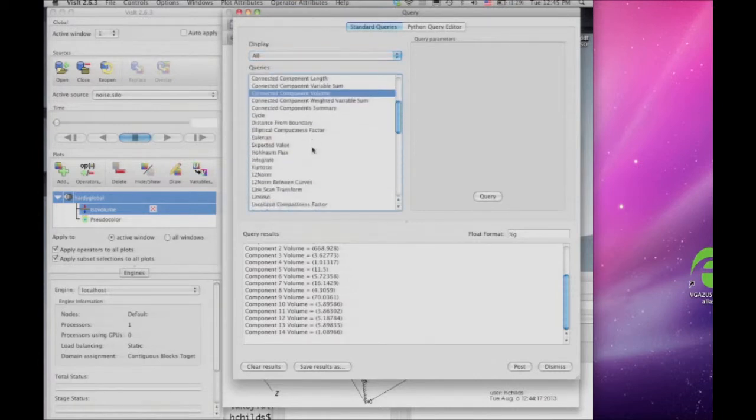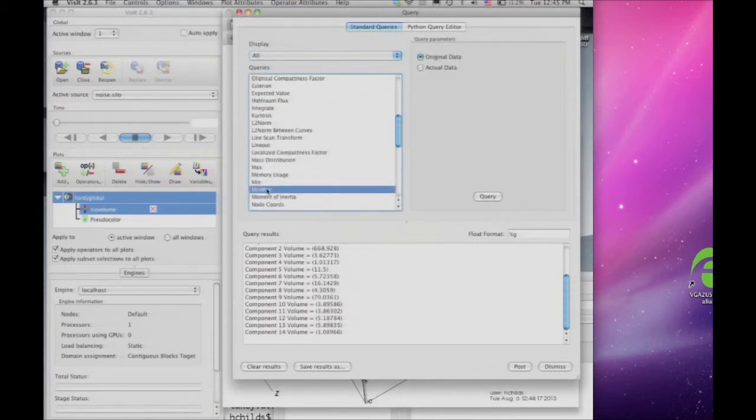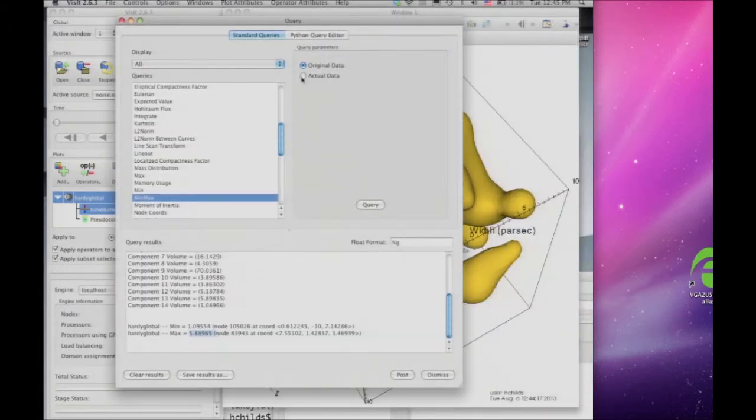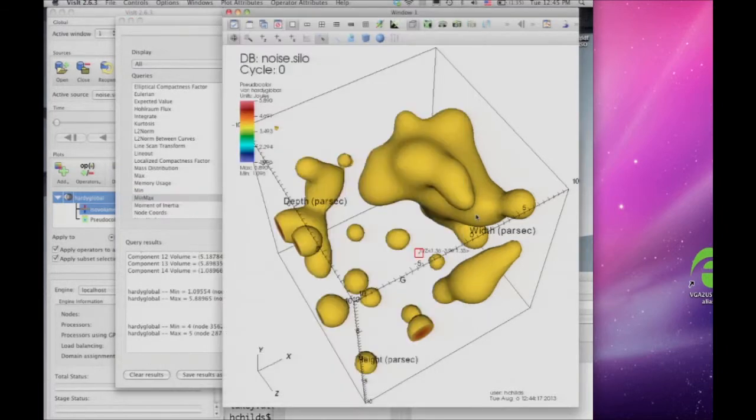These are the attributes for this isosurface operator, but these are the default attributes. What I really want are the attributes of what's currently being plotted, and if you put that 1 in there, that's what you get. It says the contour value is 2. If I do iso contour value equals 2.5 and set operator options with iso, then we get a different isosurface.